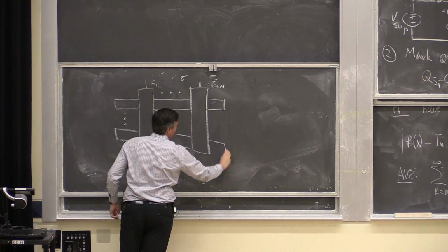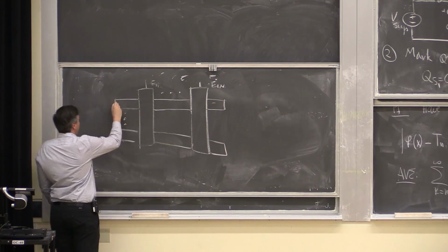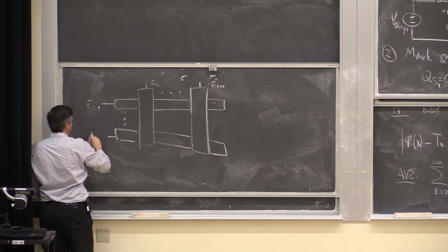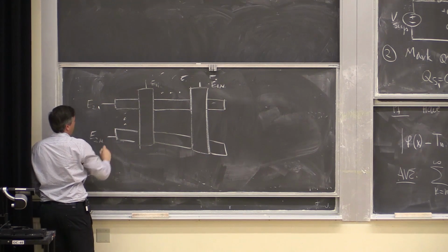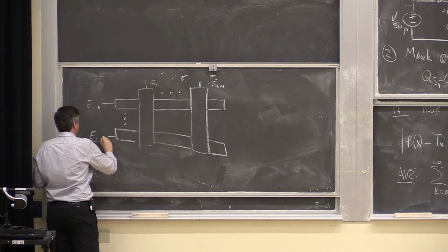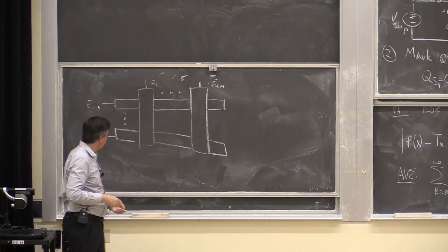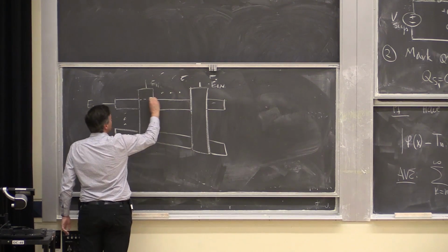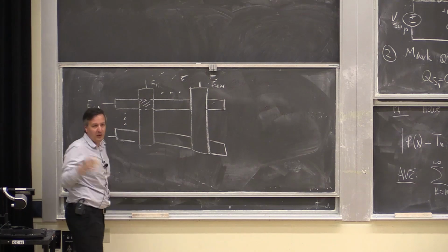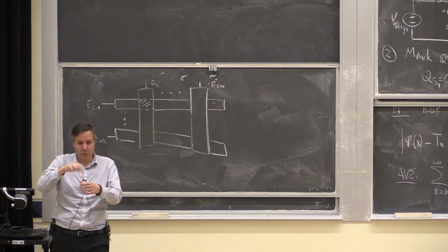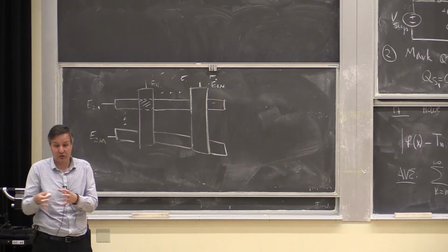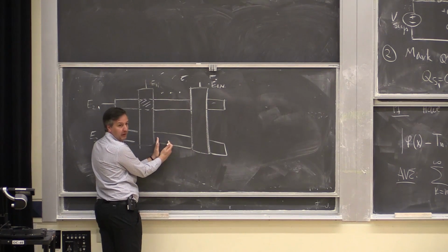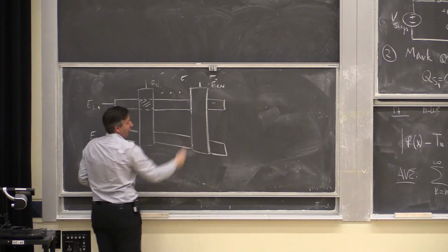So it's basically, again, the whole screen is weaved, right? And so this electrode is E21, and this one is E2N. It could be N, it could be M, whatever, right? So it's an N by M type of screen. You can view each one of these points here as your little pixel, right? It's a pixel where the detection happens. That's your resolution. And there will be one wire right almost next to it, but not touching, all the way to the Nth wire.